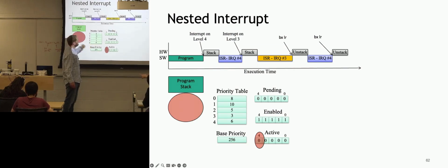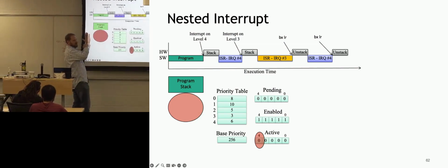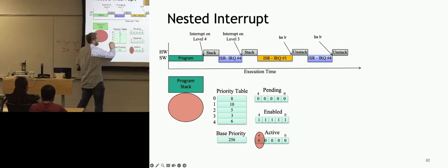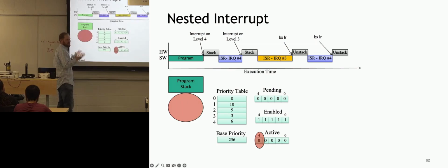And what do the 4 or 3 mean? Is that connected to a pin or something? Yeah, these are essentially signals that come to the NVIC. Number 4 corresponds to this particular interrupt priority. If you look in the vector table, those lines correspond to those particular interrupts, and each interrupt has registers associated with it, which are pending, enable, and active. The NVIC is keeping track of how they're all coordinated together.